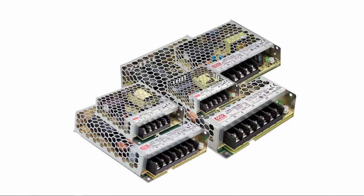Power supplies. Now these are NEMA 1 power supplies, meaning that they're open frame. You know, they're not dust proof, they're not waterproof. They're very inexpensive. These run anywhere from $10 to $50 depending on how many amps you want. Obviously, the bigger the frame, the more current. The part number usually includes the voltage and the wattage.